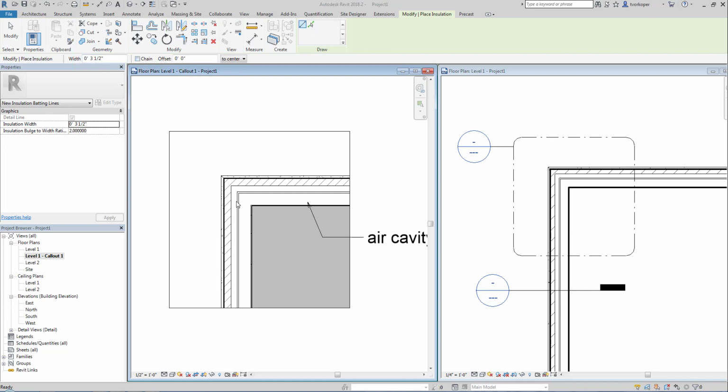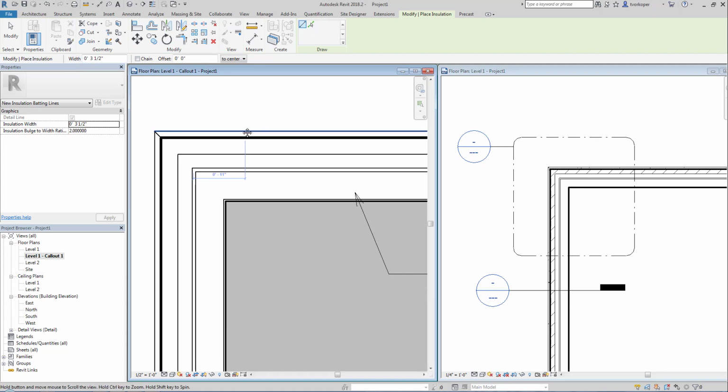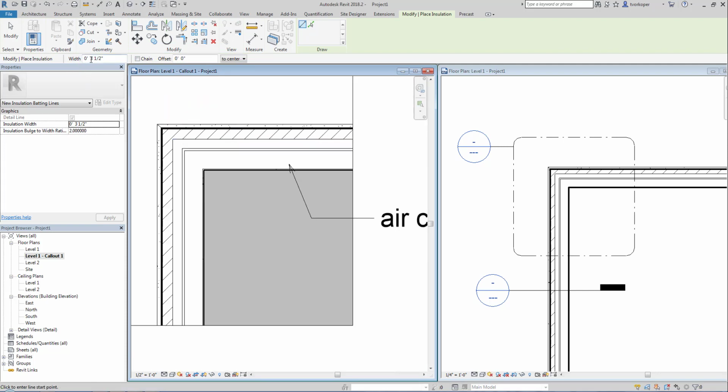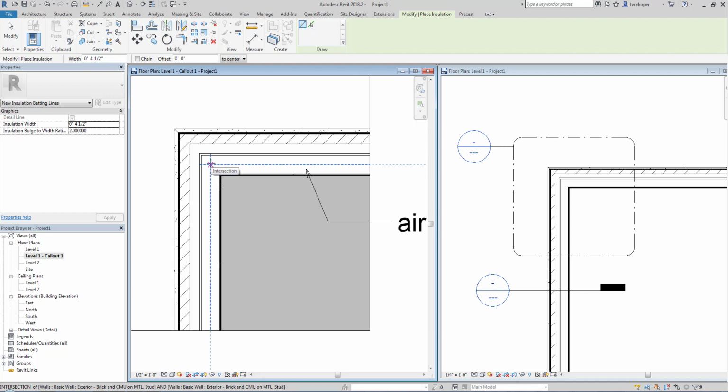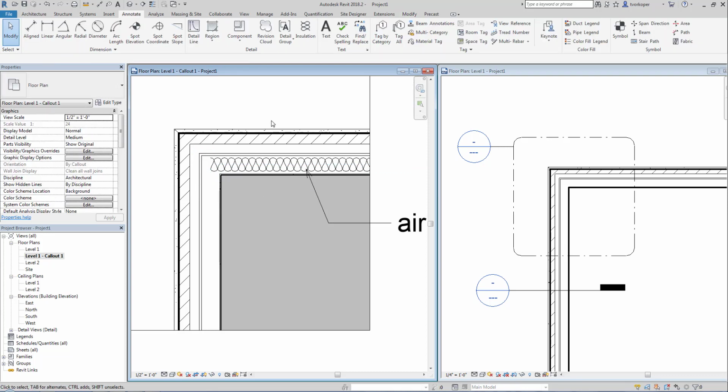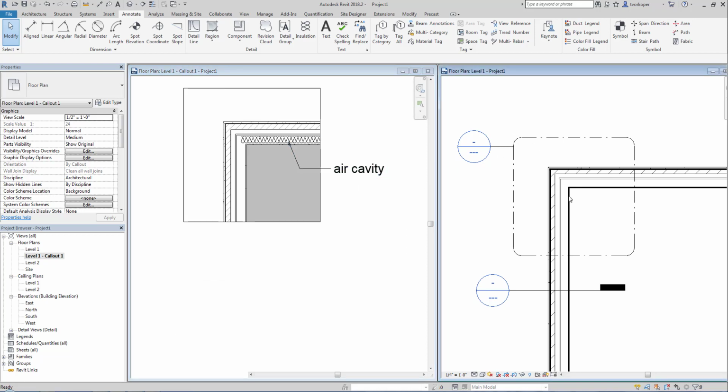We'll go ahead and zoom into this wall. We'll change this width to 4.5. And as I get close to this wall, it'll find center lines of either the materials or the core or the entire wall that it can snap to. This is nice because when I left click and slide my mouse and left click again, I can get a little lock here.